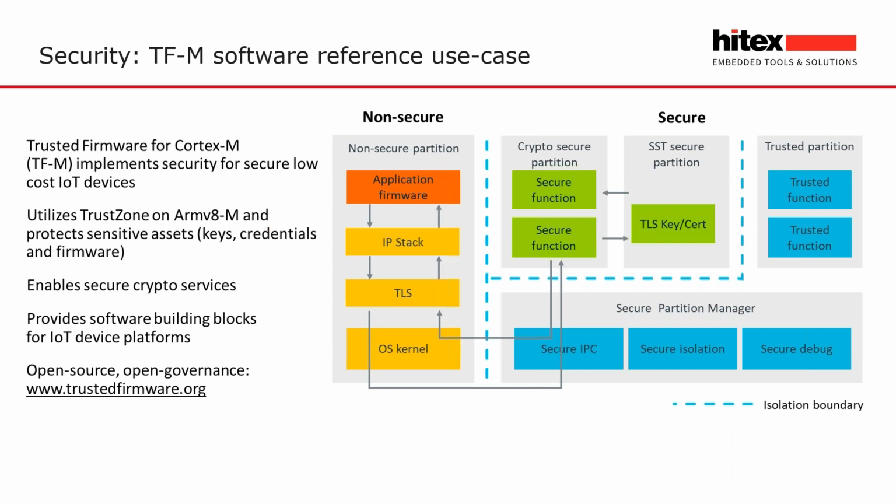So what we're going to have a look at tomorrow is the overarching security model and the trusted firmware for the Cortex-M33. This implements a secure partition manager. So we have a limited entry point to the secure partition. And then all of our crypto services are running in their own partition environment. And we can then further lock these down with memory protection regions so that we can create higher levels of security.